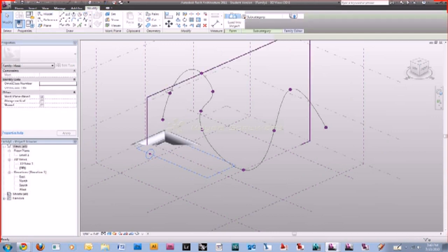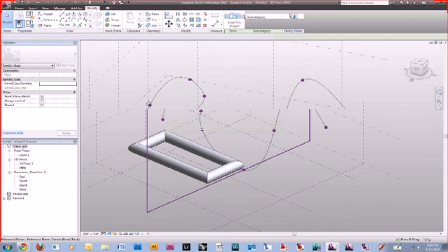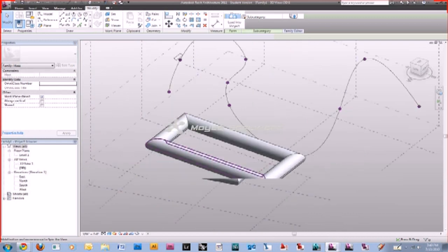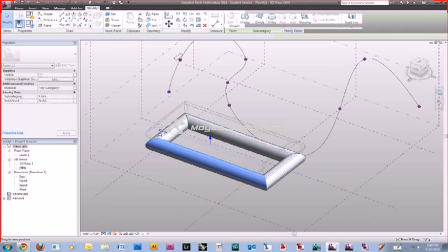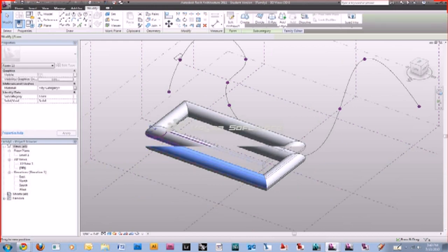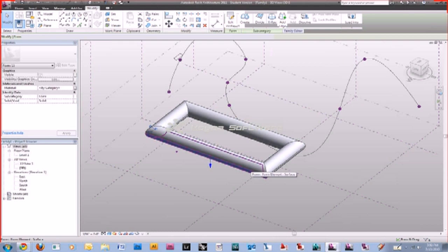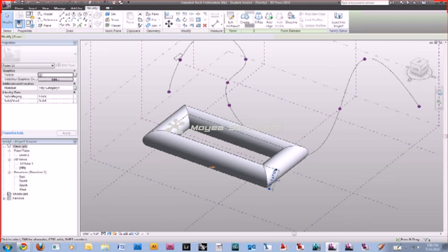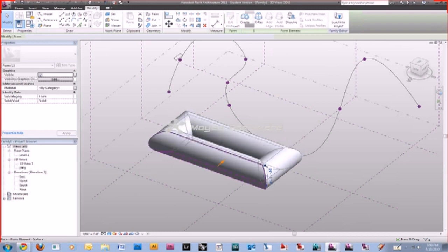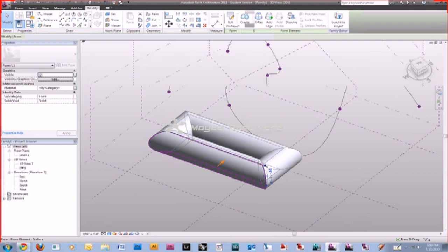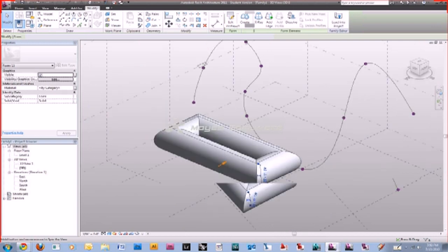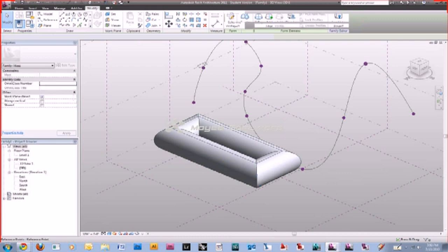It's kind of like millwork, which we'll get into a little bit later with something called adaptive components, or curtain panel systems would be another thing you could use this for. So you could create a parametric curtain family, edit it in a family editor, not inside the conceptual mass, and then you could apply that to an entire wall, a repeated shape over and over and over again. So it can end up being something that's really dynamic if you really put your mind to it.